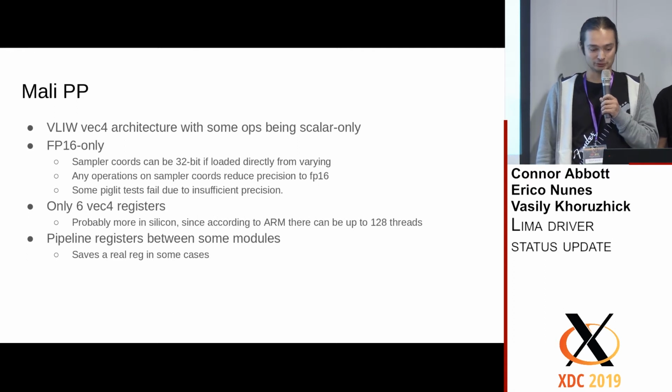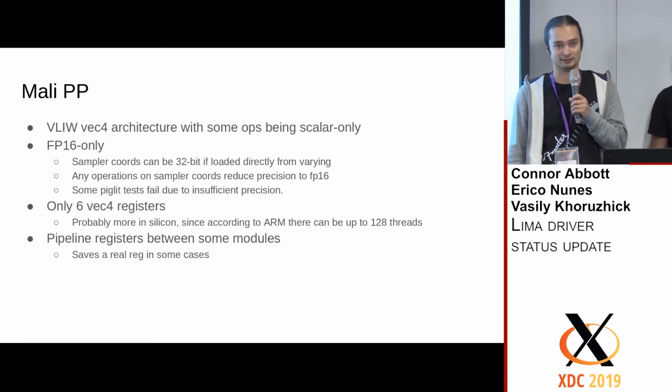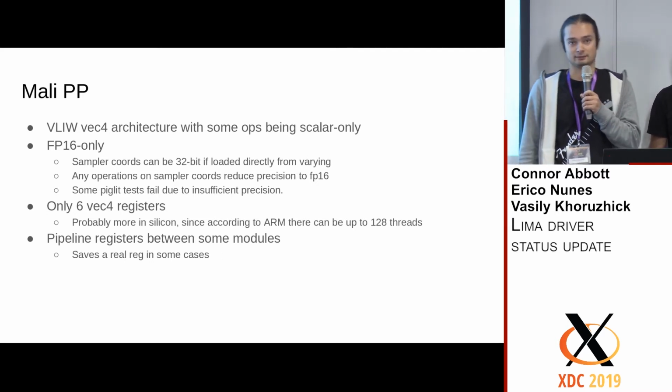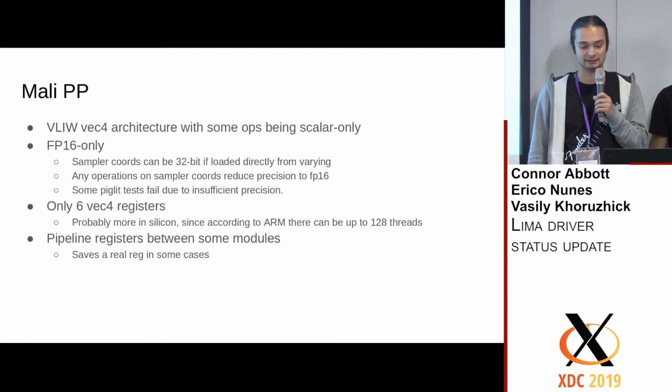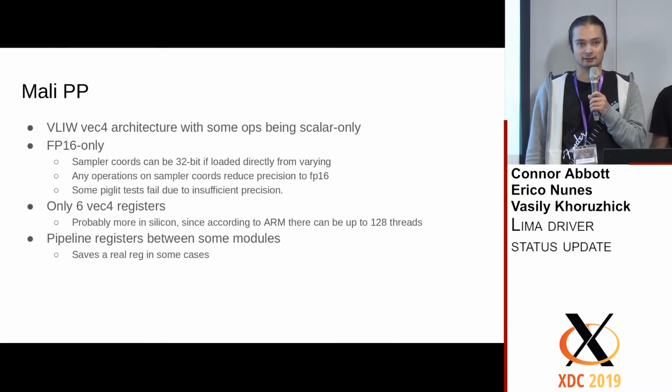There is also another issue. It has only 6 VEC4 registers, but I guess they have more in silicon. Their site claims that it can spawn up to 128 threads. So yeah, I guess it's 768 in total in silicon probably. And there are also some pipeline registers, so they are not physical registers. You can use them only within a single instruction. And if you do so, you can actually save a physical register in some cases.